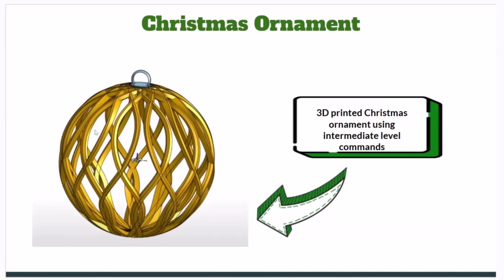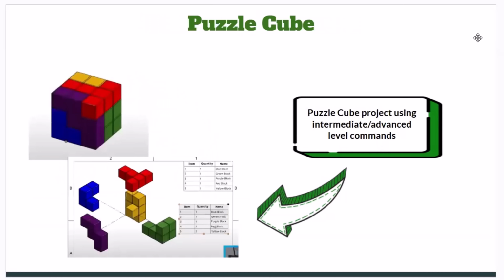And then the other one is a pretty common project, the puzzle cube. What I do in my classroom is the students create the puzzle cube using some Boolean operations, using some combine tools. They create all 27 cubes using some repeat patterns, and use Boolean operations to combine those into shapes. We can then extend that into exploded views, drawing files and parts. The students export those PDFs to a partner, and then they have to recreate their partner's puzzle cube using that drawing file.